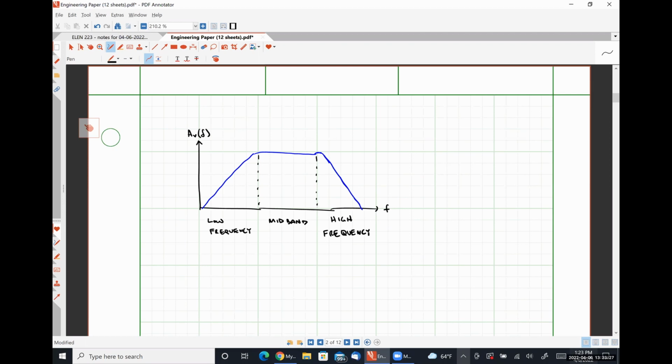When we talk about things like feedback amplifiers, effectively what's going to happen is that every capacitor in these circuits is going to cause either a pole or a zero in our frequency response. Sometimes these poles and zeros are in convenient places, and other times they are not, and they cause the circuit to behave very poorly. So we are going to learn about a concept called the Miller effect and frequency compensation.